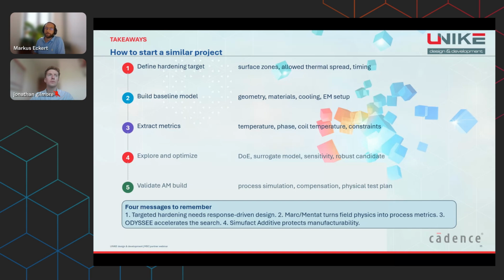How would we start a similar project? First, the hardening target must be described precisely: which surface zones, what acceptable thermal spread, and what time-dependent process. Next, a baseline model is built, including geometry, material data, cooling, and electromagnetic setup. In the third step, metrics are extracted: temperature, phase fractions, coil temperature, and manufacturing constraints. Only then does systematic exploration with design of experiments, surrogate models, sensitivities, and robust candidates become useful.